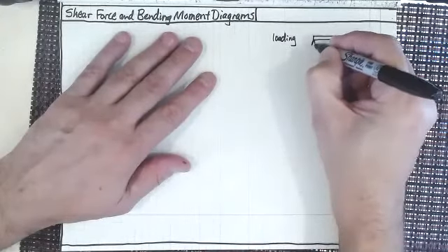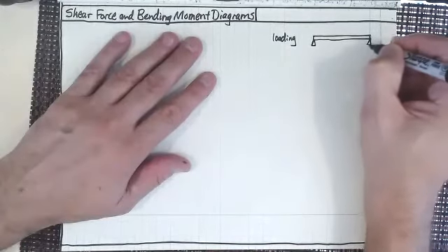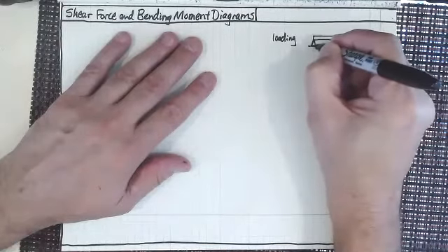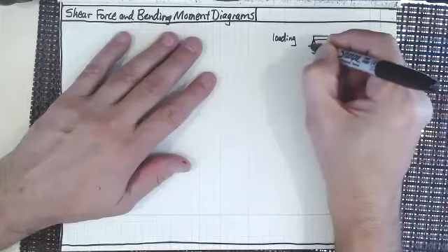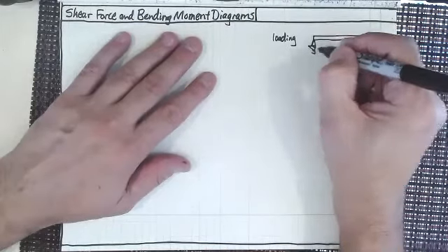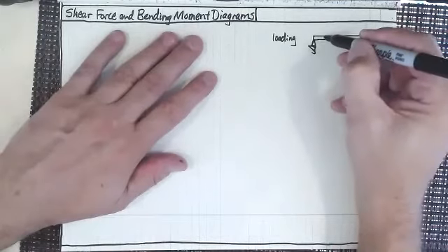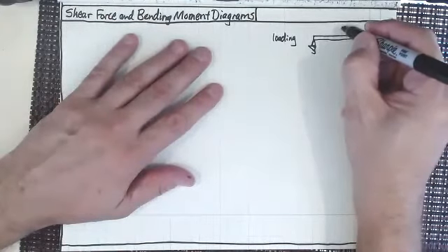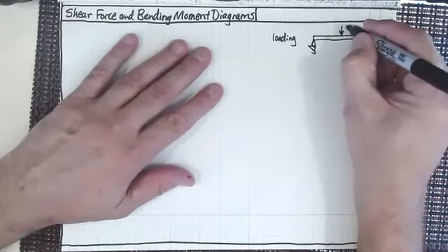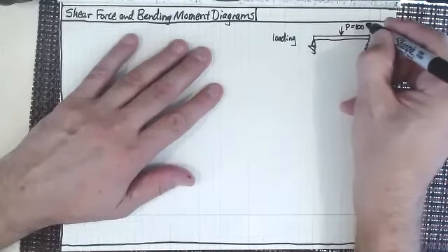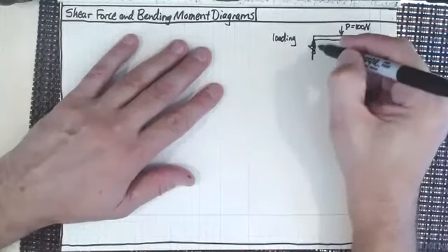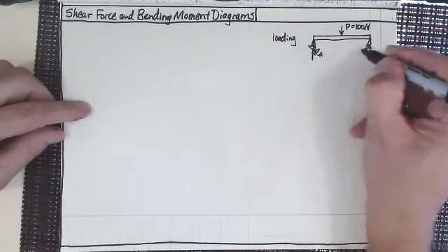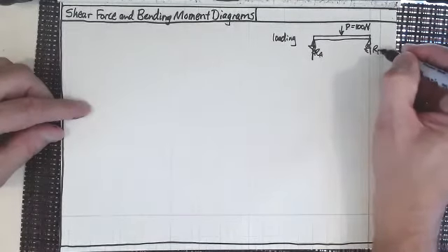So let's just look at this. It's called the loading diagram, and I think everybody understands why, because it's where the loads are. So we're going to place the loads, and in fact, this is 1, 2, 3, 4, 5, 6, 7, 8. What do you know? I made it one less. But the good part is that I now can draw the force P, and I think we made P equal to 100 newtons, and then that made the reactive forces R sub A and R sub B. It's only supported by these two supports here.